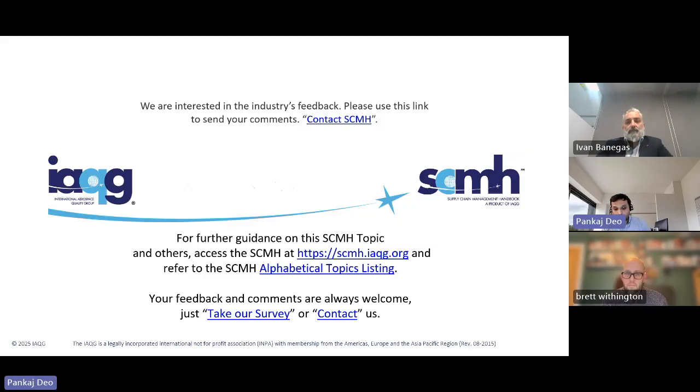And for me, just to add to that, the key is the close coordination between supplier and customer right from day one. The earlier you connect, the earlier you coordinate and define your scope on 9145, the easier it's going to get. We could avoid so many future issues in serial production if we start collaborating well in advance, identify the design risk, the process risk, and the risk in the supply chain, and make sure that we eliminate those in the first 4 phases of APQP.